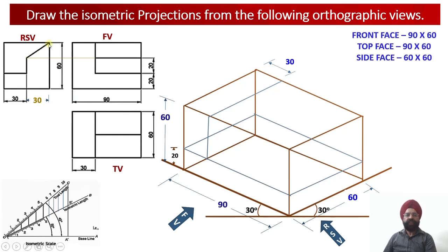So please check, the slant portion is starting from this rear corner. So rear corner is this one. This is my rear corner and this is my rear corner, so the length of the slant portion should be how much? It is equal to 60 millimeter. So this was 30, so this is 60 millimeter, right? So here I have got 60 millimeter as the length of this slant portion. And another thing, I know that this slant portion will be ending at a distance of 20 millimeter above this first ring which I had created.